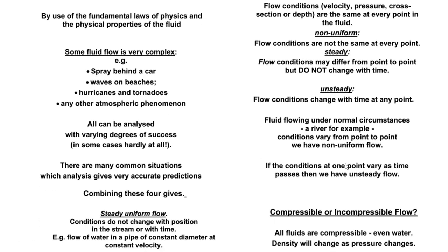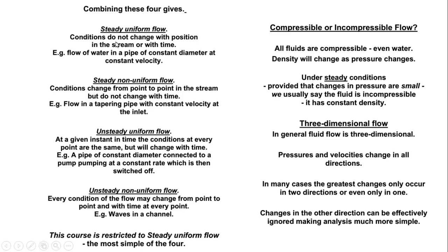Then there are some other scenarios where we can combine both steady and uniform. If it's steady, it does not change with time, and also the flow is constant at any given position. Steady, non-uniform: you have to look at steady in relationship to time, and uniform in relationship to position. Then we've also got unsteady, uniform.